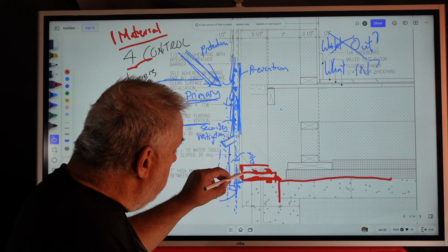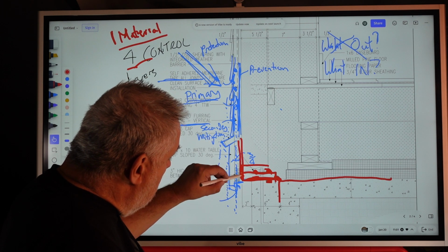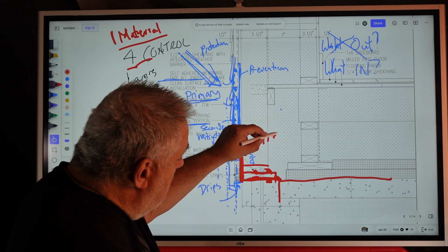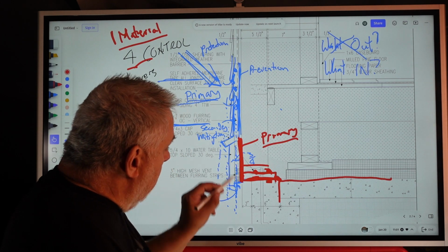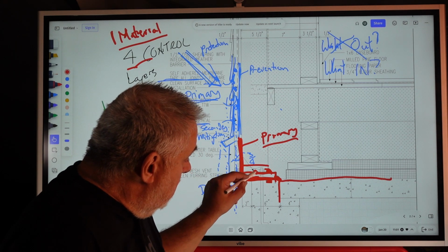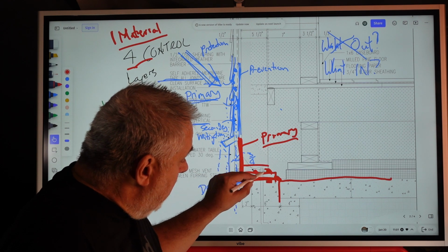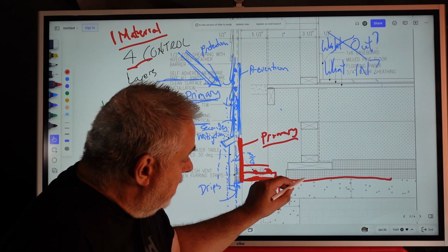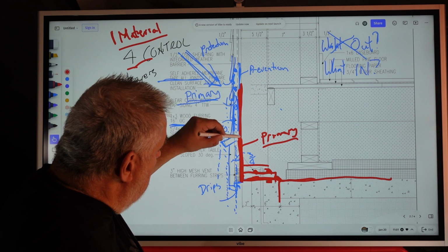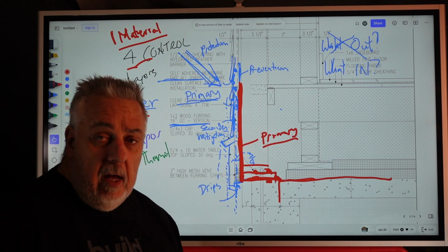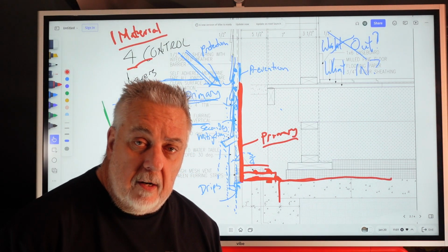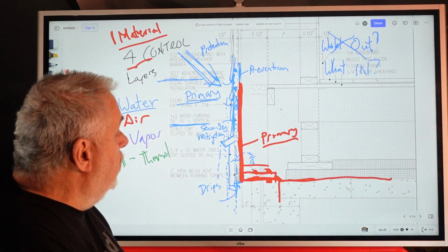But through all of these beads of sealant, we now have our zip sheathing here. And that is our primary, and actually that is our only air barrier on this house. And that connects, through a series of sealants, to our slab, goes across the building, and basically goes up. And when we get up to the roof, we'll pull up the eave detail and we'll run through this exercise again with the control layers there, so you get an understanding of how we go across the roof.